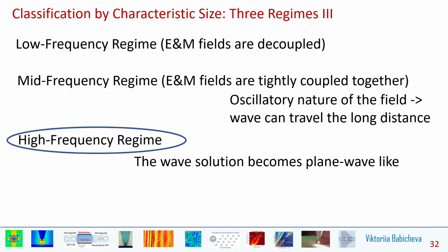So alternatively, we can think of rays as being particles, and this is what happens to light rays. Consequently, these so-called light rays can be described by the transport equation and the eikonal equation. These equations can be derived from the wave equation under high frequency and short wavelength approximation. The high frequency regime also allows for the beamforming of electromagnetic waves. For instance, in the case of optics, the electromagnetic fields can be focused, and antennas with high directivity such as reflector antennas can be designed at microwave frequency. At low frequency, such an antenna has to be unusually large to increase electromagnetic wave directivity.